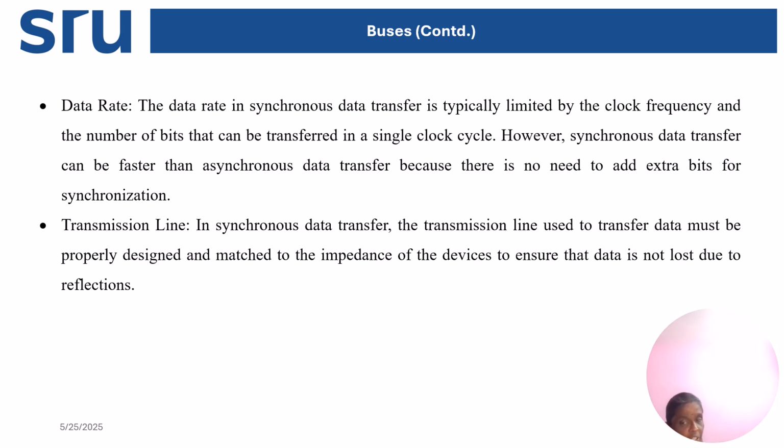But in synchronous data transfer, only data is transferred along with the clock. The clock is enough. There is no need for a sync pulse to indicate the starting clock or the ending clock. No extra bits are necessary.